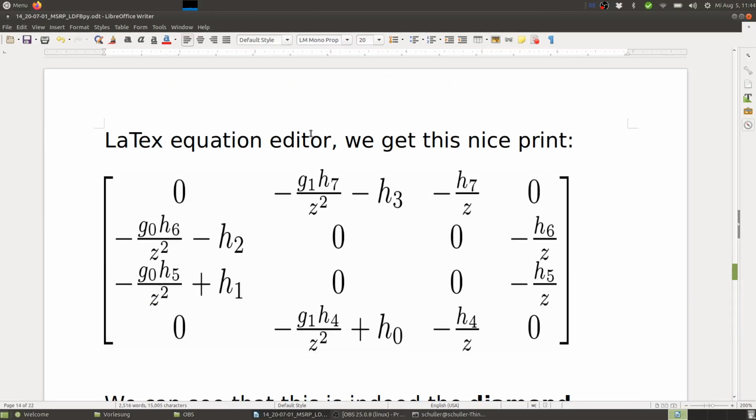So this is a nicer notation here, and you can see it actually is suitable for documents. And again we see here we get z to the minus 2 as the highest exponent of the polyphase matrix, of the folding matrix, and that means we have longer filters now.